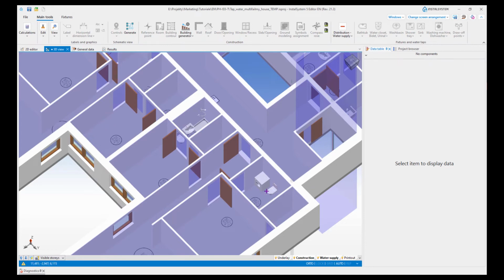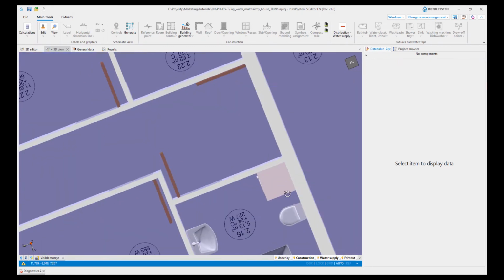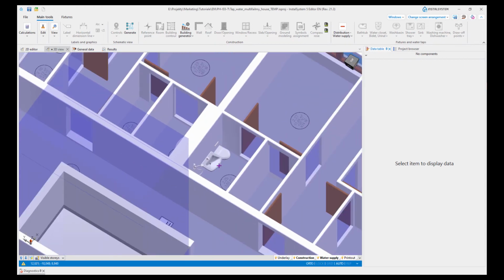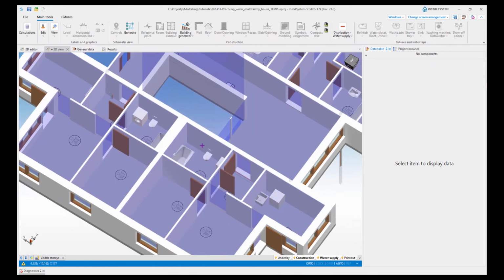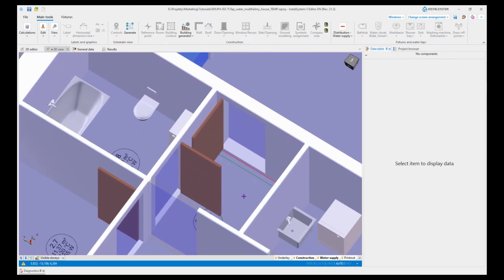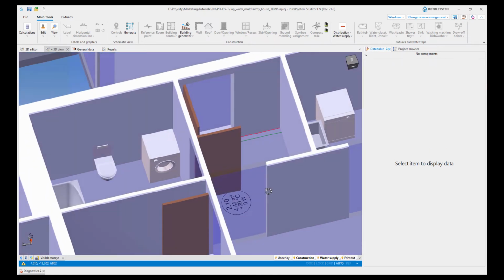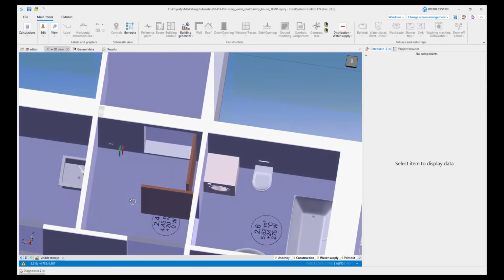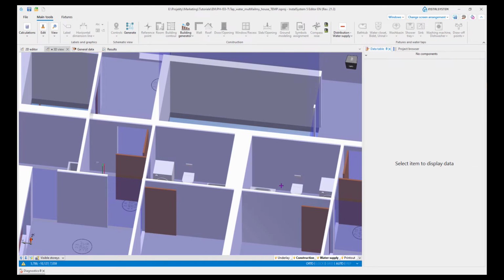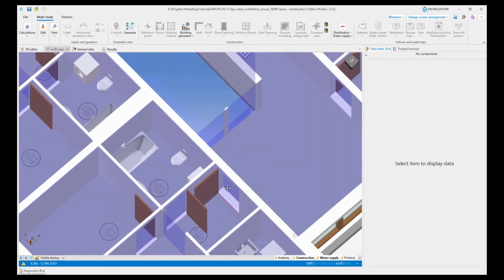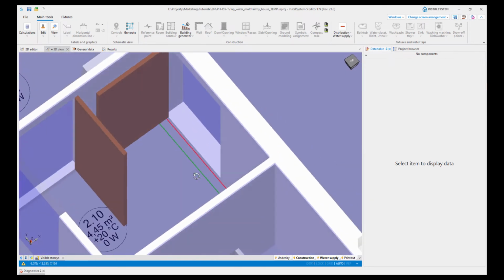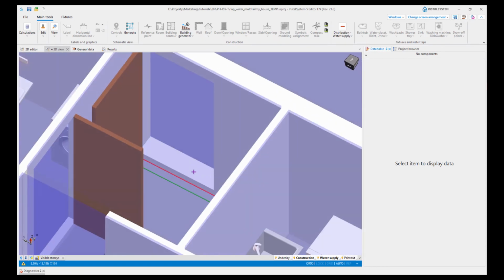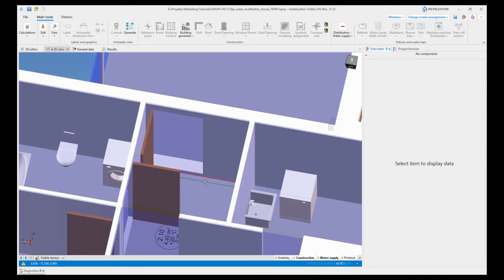these two edit scopes, and we can check one by one all the rooms. And if you take a look now at this part of the installation we have just entered, you can see in some places that the pipes are visible, which means that probably we should change the elevation of some sections of these pipes.